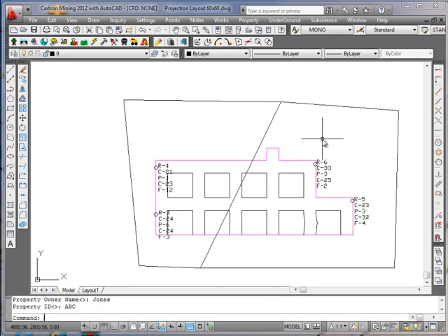So now that we have the offsets that have defined the pillars and the outside of the mining area, and we've located and taken thickness measurements for the coal sections and placed property boundaries, we're ready to calculate the tons that were mined in this area.